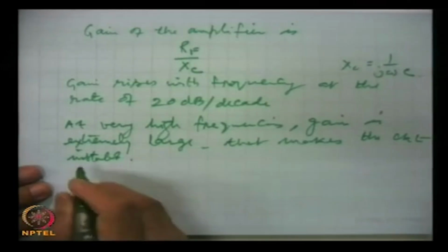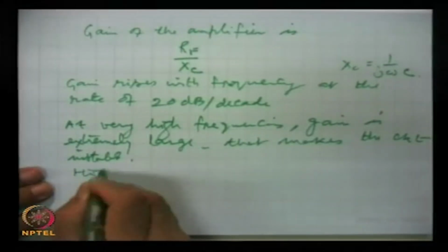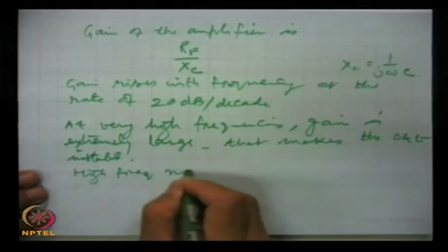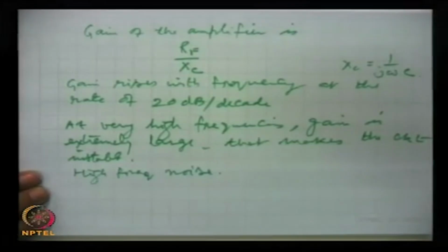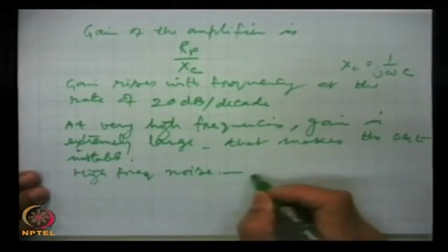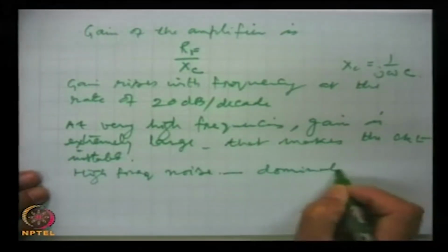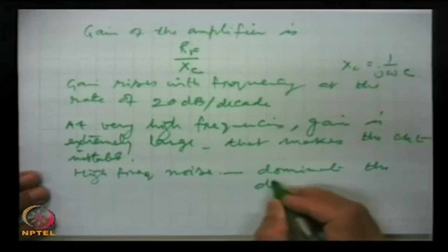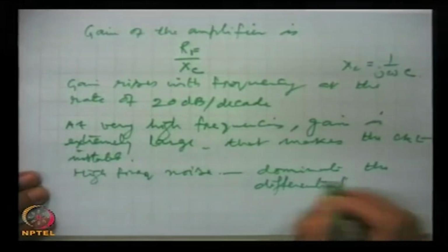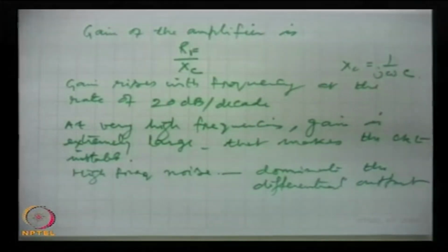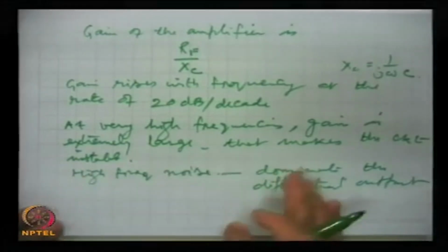Because of this there is high frequency noise which will be heavily amplified, and that will dominate the differential output. So it will not be an accurate differentiation at very high frequencies.